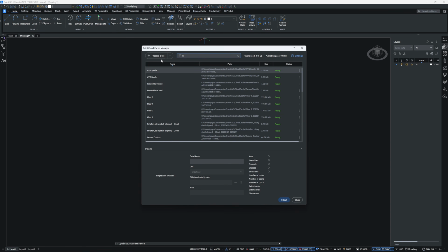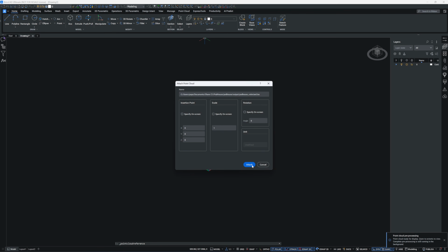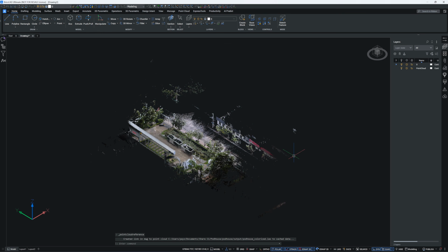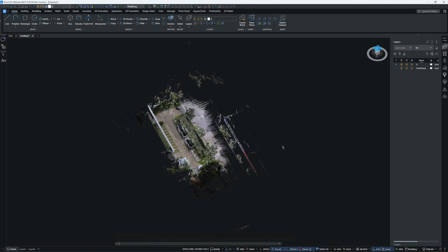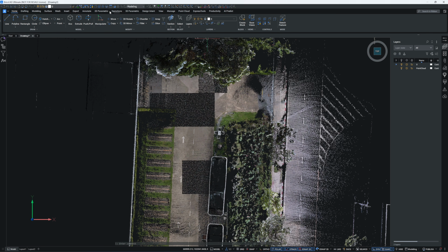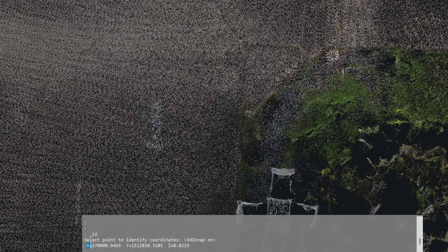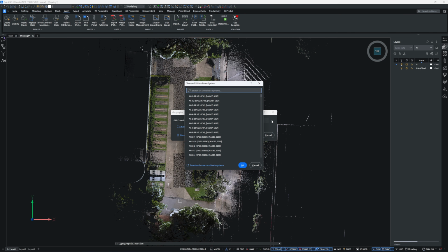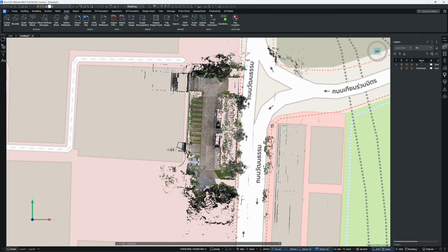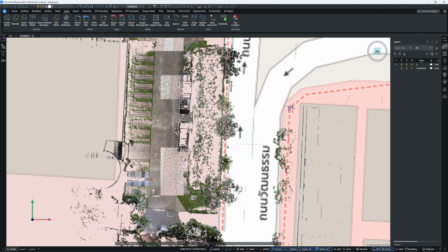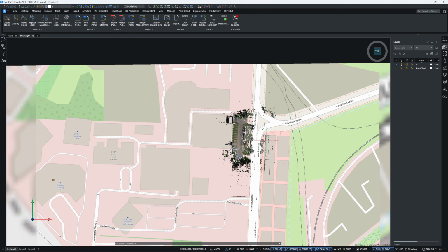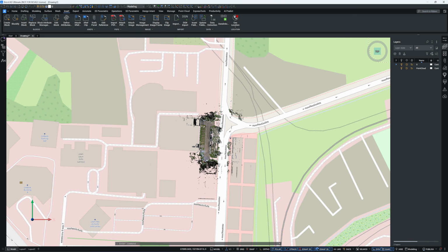This is BricsCAD, the lowest cost CAD tool that can import point clouds directly from a 3D scanner. Even with a massive dataset of over 200 million points, you can still orbit the viewport fluidly. Each point in the cloud is aligned with GPS coordinates, including the orientation to true north. It also has an option to overlay the street map onto the point cloud. This makes it easy to trace the road network and integrate it into the master plan without actually scanning the road in 3D.